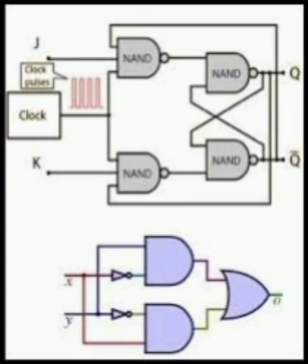Look ahead carry adder makes the addition faster. It is based on two additional signals that must be computed: generate signal Gi equals AiBi, propagate signal Pi equals Ai XOR Bi, and the carry signal generated Ci plus 1 equals Pi Ci plus Gi. The number of AND gates required in the carry circuit for an n-bit adder is n(n plus 1)/2. The number of OR gates required in the carry circuit of an n-bit adder is n.